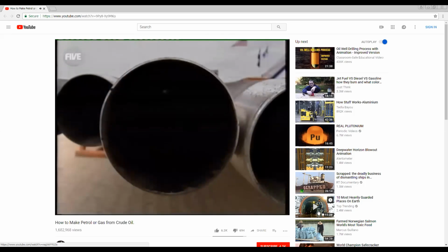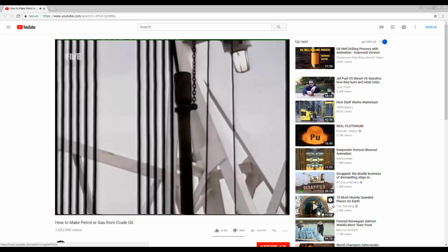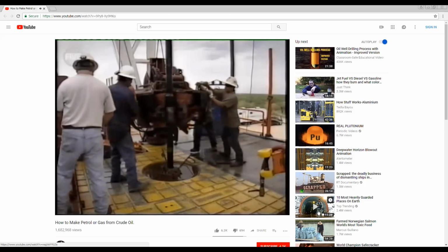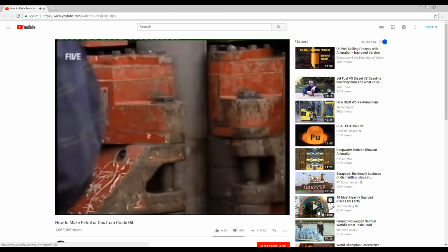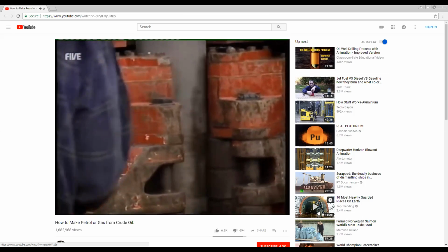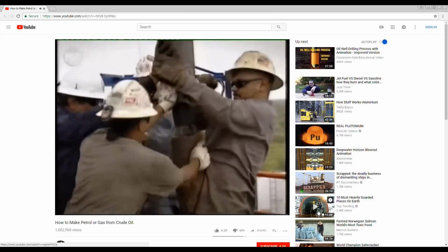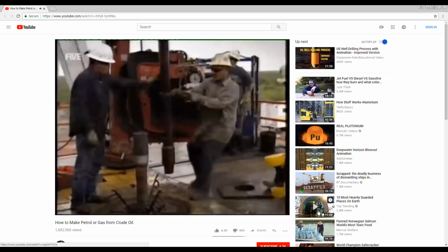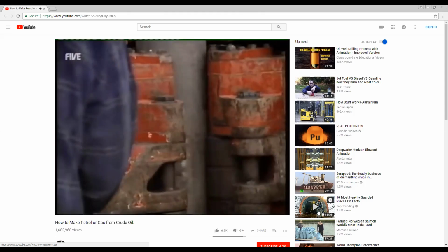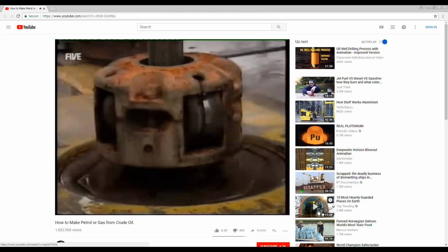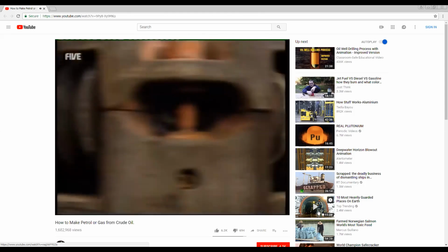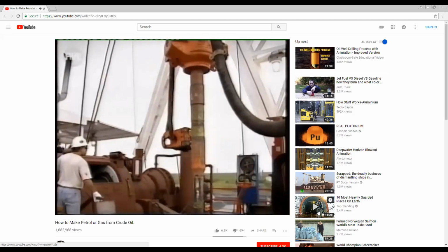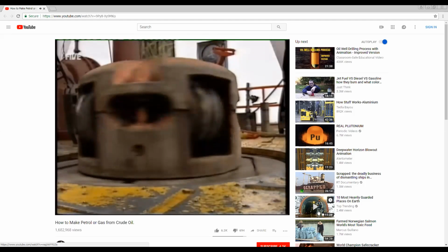As they drill, the team need to regularly attach new 9-meter lengths of drilling pipe using an enormous 5-ton automated wrench called an iron roughneck. With the drill head burrowing at around 5 meters an hour, this arduous task must be repeated every couple of hours, 24 hours a day. The drilling is only intermittently halted to line the well. Eventually, if they're lucky, they strike oil.